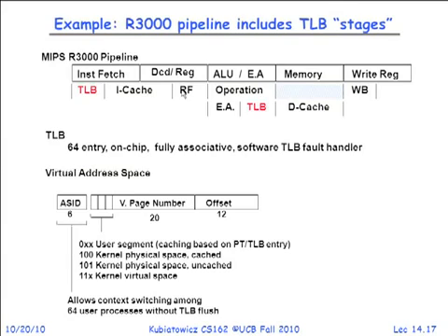Register file access was at the very end. And then when did we do the memory TLB lookup? Well, here we compute the effective address. We do the TLB lookup on the half cycle before we do the memory cache lookup. So by playing with the pipeline in the R3000, they were able to hide the TLB lookup in a half cycle before you went to the cache. And that was how it basically didn't impact the speed much.